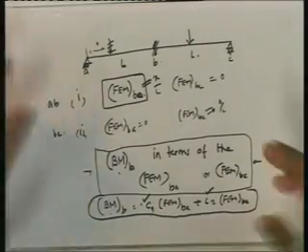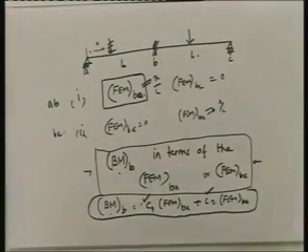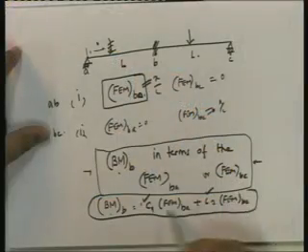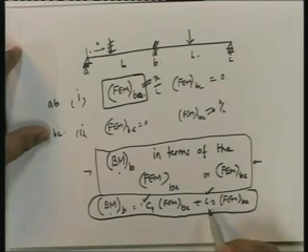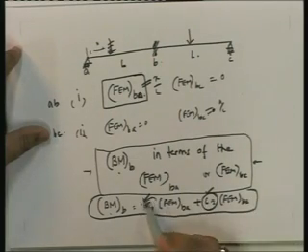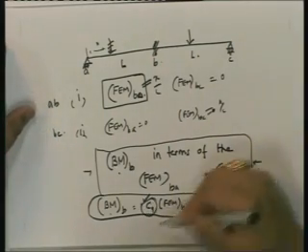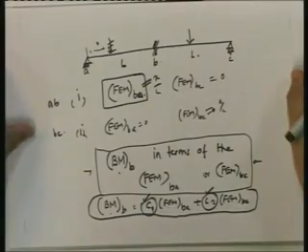I can find out the bending moment and make it statically determinate, both AB and BC are statically determinate structures. Okay? Suppose it's between B and C, then this would be 0 and this would kick in. So all I need to do is really find out C1 and C2. If I can find out C1 and C2, I've solved my problem.